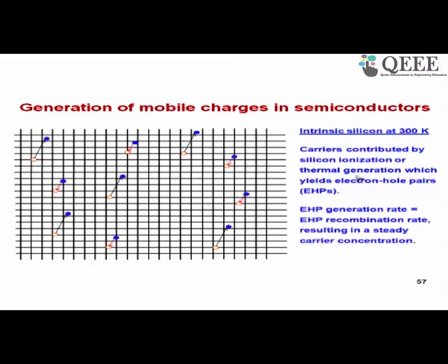But so how can the silicon not blow up and bonds keep breaking? Evidently some bonds which are broken are getting re-established, right? That process is called recombination, when a free electron jumps into a vacancy. That is what is shown here. The arrow from a solid dot, which is an electron, getting into the vacancy or a hole is a recombination process. So you can see that for every electron hole pair generation, there is an electron hole pair recombination happening somewhere else.